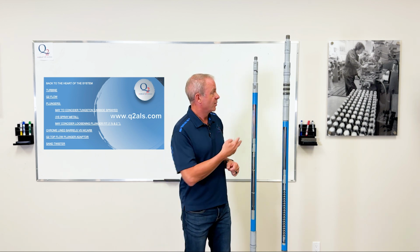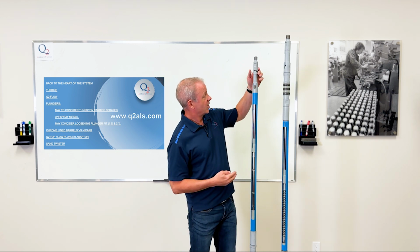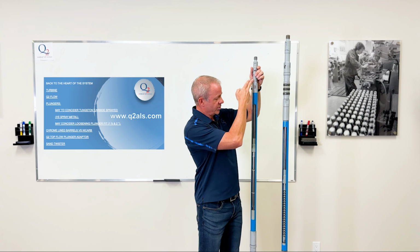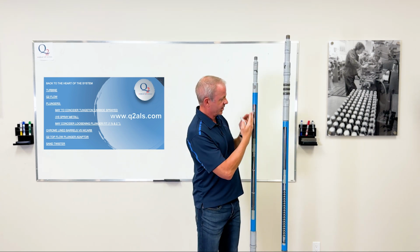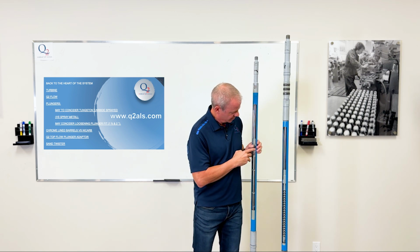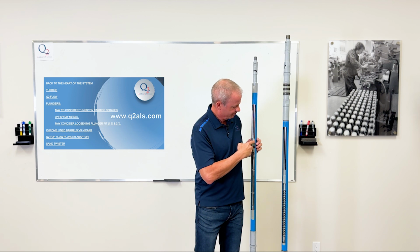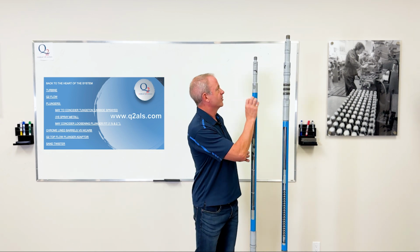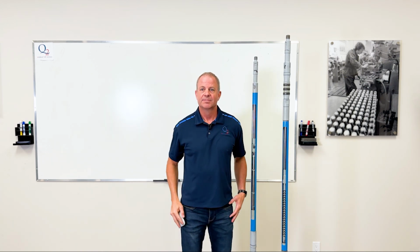And on this one here, I think there's a Q2 flow plunger adapter up top as well. That turns the fluid here. Any way we can turn the fluid through these pumps to get all of the solids distributed around the annulus properly. This example here, you can see that the solids would come down here and it would actually come on this ledge, and we don't like that. So we'd like to have it turning all the way through and up through here as well, just to keep it suspended in the vortex.